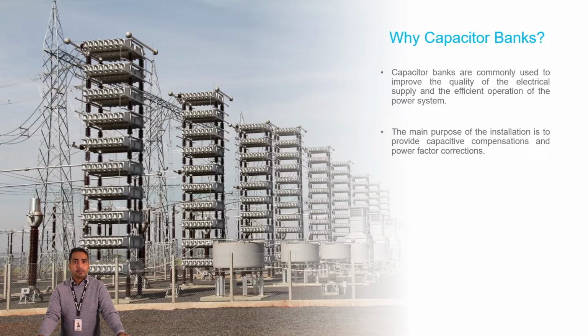We all know that in big industries, there is a large amount of inductive loads, like inductive machines. They need to consume a lot of reactive power. So the industry needs to use capacitor banks so that they remain within the limit of their power factor, because they are penalized if they do not follow the grid codes.